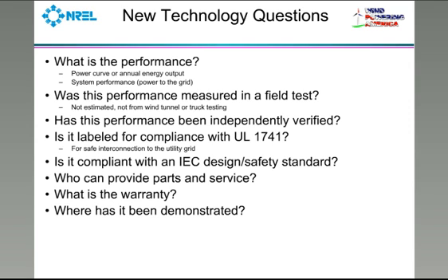You're probably not going to get an answer to this question, but in the old days, a common way to get the power curve was a manufacturer would put the turbine on a stub tower, and a guy would hold it in the back of a pickup truck. And the pickup truck would drive at various speeds, and they'd measure the power output. That's really not a good way to do it, and so they're going more towards real field testing.